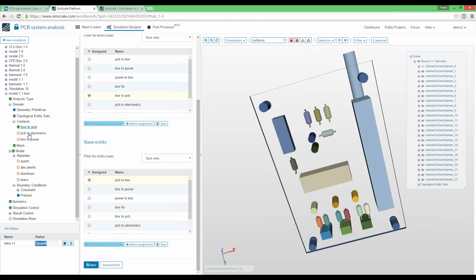You could have, let's say, well, we would have to have a representation of these two parts very close to each other. You could define a particular type of contact that would disallow the thing to move. But in this case, you could perform the harmonic analysis and visualize when the parts are overlapping. Or there is the advanced dynamic analysis, which I will not be covering today because of the time constraints, where you can define the real physical contacts, and you will also see the stresses that are happening when the parts would hit each other. So there are possibilities of doing this kind of advanced simulations.